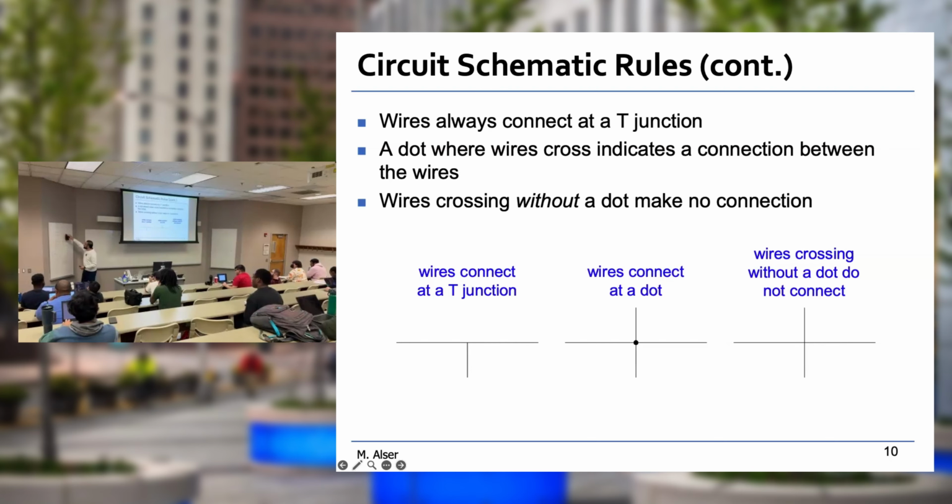But we can connect one of the outputs to an input of a gate, for example. We could pick this output and connect it to an unlimited number of inputs. That's fine. And this way you can add a dot over there if you want. In this case, it's optional because that's the only source for those wires, so it's up to you to add these dots or ignore them. It's legal to connect the output of one gate as input of many other gates.